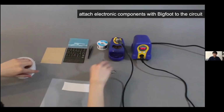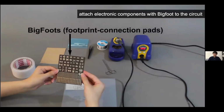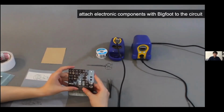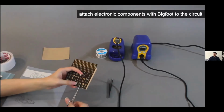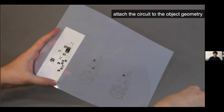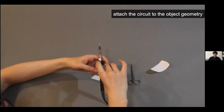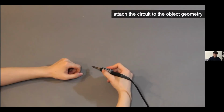You should put on some double-sided tape for later object attachment. Take out the Bigfoot, solder the corresponding components onto the Bigfoot, and then apply the Z-axis tape onto the back of the Bigfoot. This is the tape that is only conductive in the Z direction. Then attach the components to the circuit, and you have it, the fabricated Morph Sensor. Next, you will go ahead and cut out the sensors and attach them to the object. That's the whole fabrication pipeline.